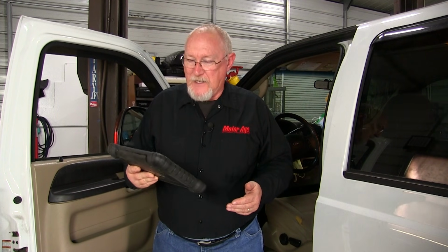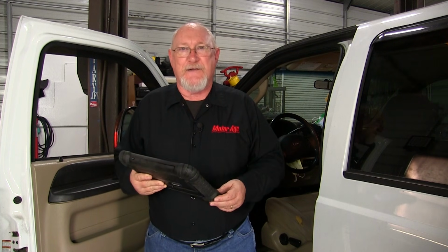The first thing I have to do is figure out exactly what kind of a problem it is that I'm trying to repair. So my first stop is going to be connecting my scan tool in enhanced mode, that is with OEM specific software, so I can access the ABS ECU and find out what code or codes are stored there.